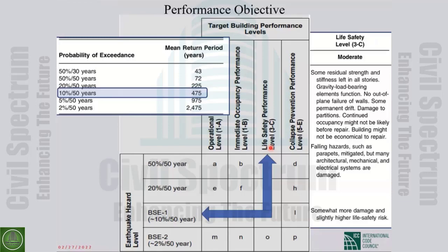The formula, for example, shear capacity of this beam, but for the material properties, we will put the lower bound characteristics for the concrete and steel if it's reinforced concrete. Then for the deformation control ones, we accept that the demand be more than capacity.